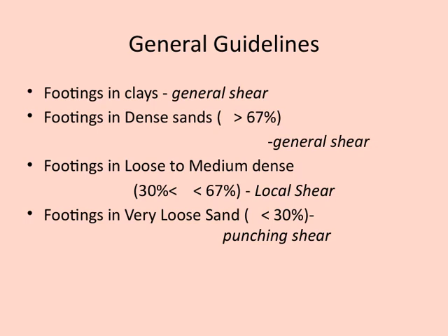Let's wrap up with some general guidelines for footing design based on soil types. When dealing with footings in clays, the primary concern is the overall shear capacity. It's important to understand that clays tend to have a relatively uniform shear strength, so we focus on that aspect for stability. Moving on to dense sands, which are those with more than 67% relative density, the key point is that they also require consideration of general shear, similar to clays, because their dense nature provides substantial shear resistance.